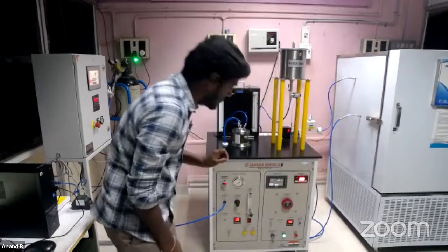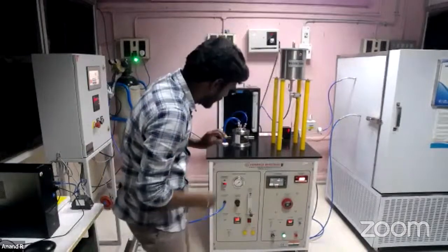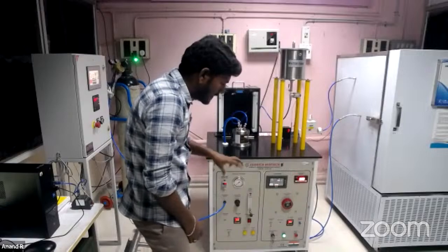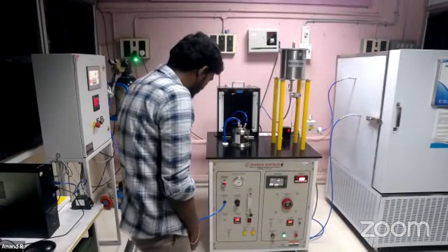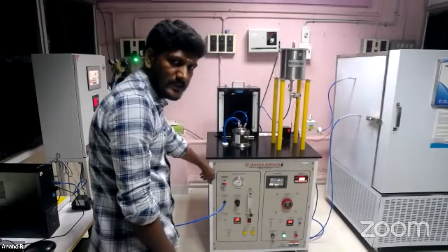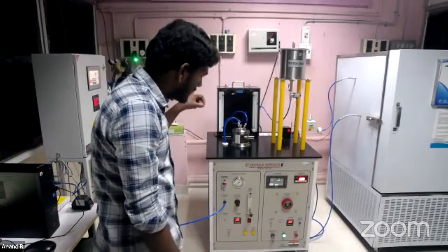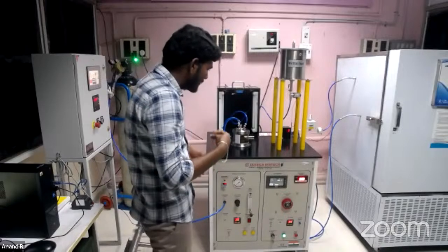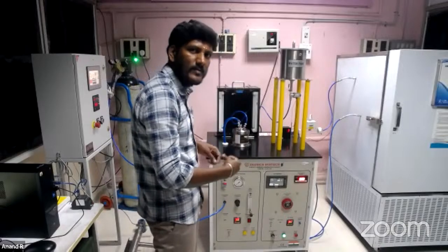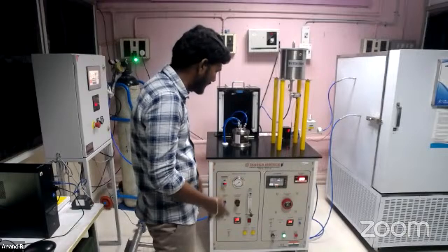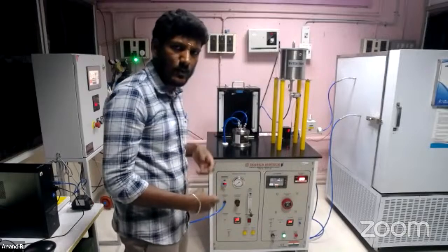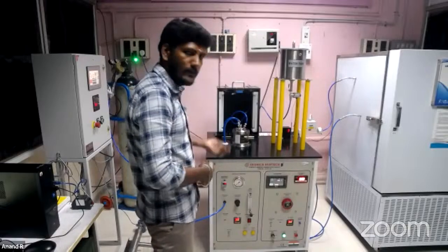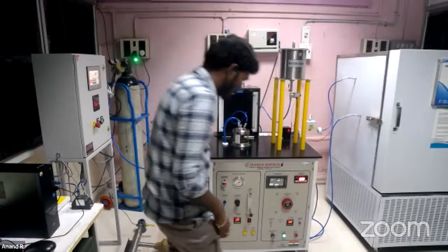The plasma reactor is already filled with water and it has a high voltage electrode and a ground electrode. In between, the electricity will be passed and the gas is also moving further. When electricity is passed into the gas, it becomes plasma. The nitrogen will be excited. It will also dissociate the water particles into hydrogen, which will link with each other and form ammonia.